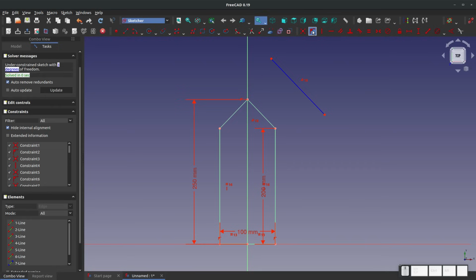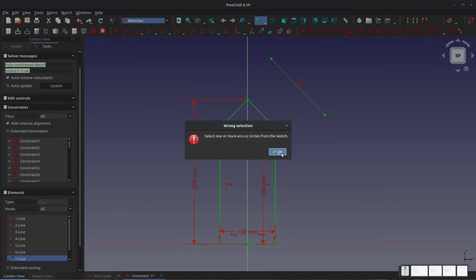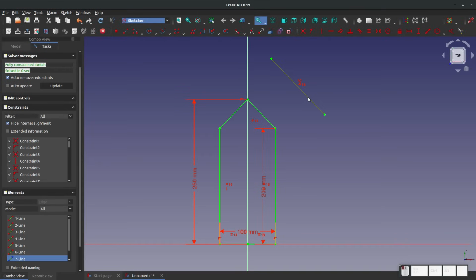So we've covered coincident, vertical, horizontal, parallel, perpendicular, tangent, equal, symmetric. This one is just another way of locking things down. And then we have the lock, which adds dimensions, horizontal, vertical, our diagonal dimension, our radius, and our angle. This is a little bit complicated. I don't think you need to worry about that one as a beginner. All right, maybe one last tool to go through. I'll change this back to driving dimensions, or white.